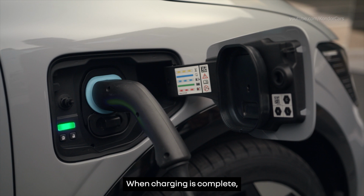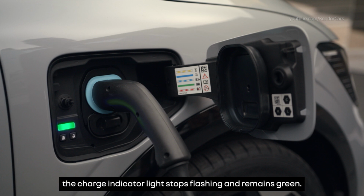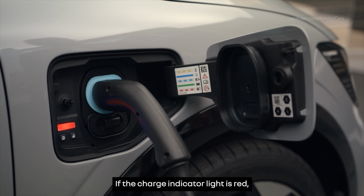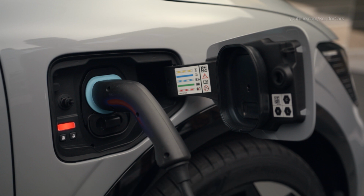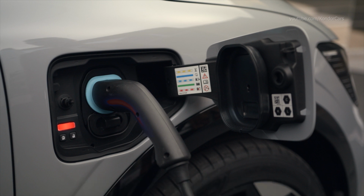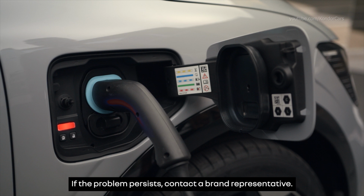When charging is complete, the charge indicator light stops flashing and remains green. If the charge indicator light is red, there is a charging malfunction. You need to connect to another charging terminal. If the problem persists, contact a brand representative.